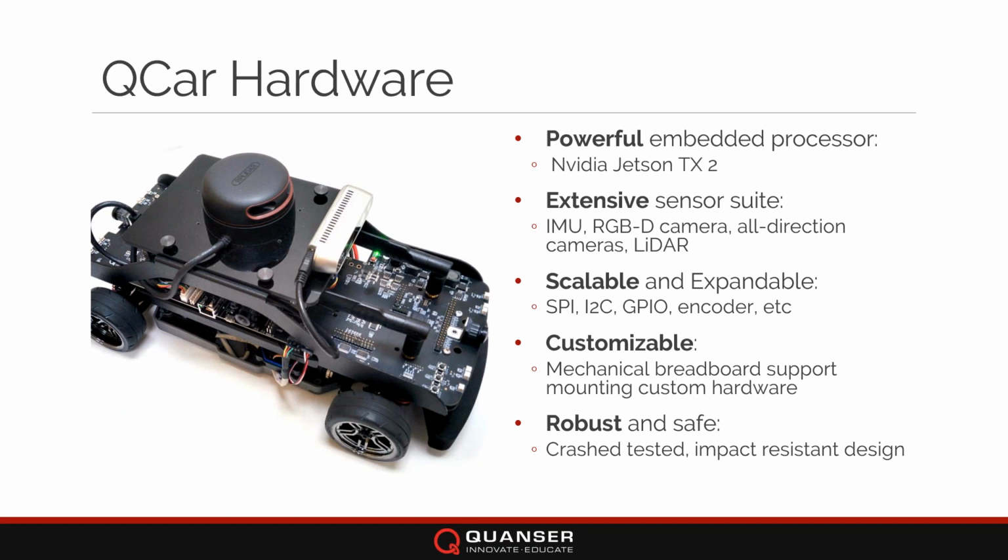And if the built-in extensive sensor suite is not sufficient, we also have built-in expandability to help scale up, with plenty of SPI, I2C, GPIO type general purpose IO pins and encoder connections available to add on additional modules. The mechanical side is also fairly highly customizable. The top mounting frame can be adjusted. You can see there are thumbscrews, so you can easily exchange or make modifications to the mechanical mounting to add modules if you need to.